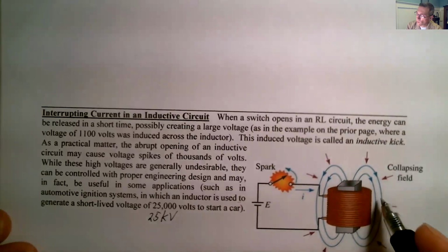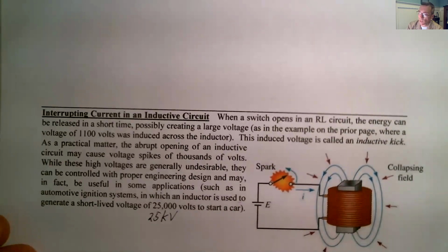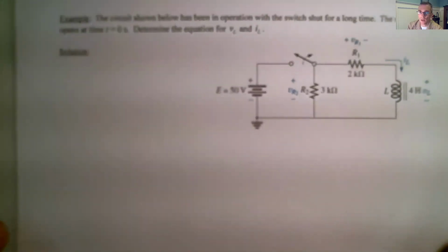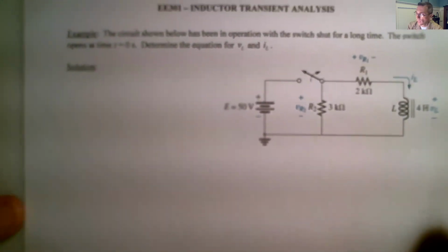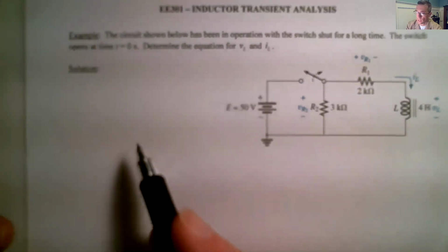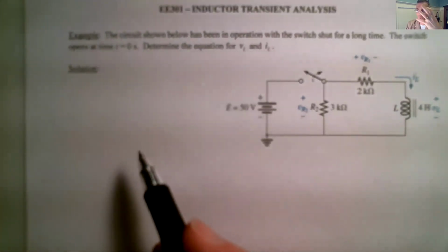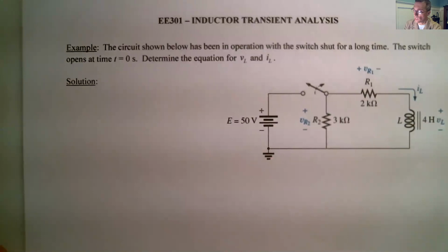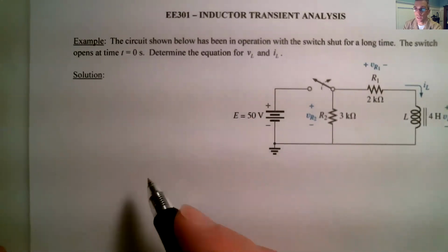Right, so that spark plug generates that voltage, and because the voltage gets high enough, it breaks down and ionizes the field inside of that compressed fuel-air mixture. What happens is there's a spark, which creates heat and it combusts the fuel.